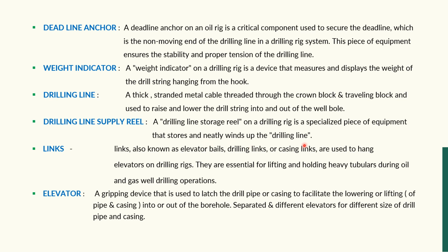Okay, we do the slip and cut operation due to the mechanical wear and stress of the drill line. Due to regular use, if there is some mechanical deformation or error in the drill line, we do the slip and cut, and it is done on the basis of the ton-mile use of the drill line.